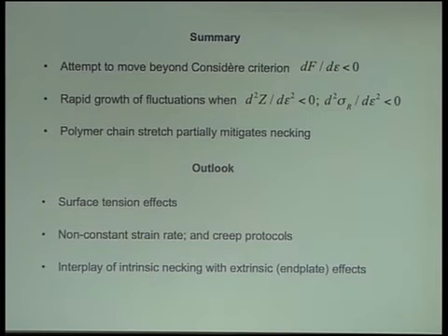In future work, I've been interested here in very highly viscoelastic filaments in which the bulk stresses dominate. But if we're thinking instead, for example, about polymeric solutions or inkjetting problems, or very thin filaments, we're going to have to think about surface tension. And of course, often the experiments are done under a constant load, not a constant strain rate, so we need to think about that too. And really, we need to do a proper, fully spatially aware simulation that moves beyond the slender filament, to think about how the mechanical necking instability that's intrinsic to the model's rheology interplays with these extrinsic effects of seeding the neck by the end plates, for example.